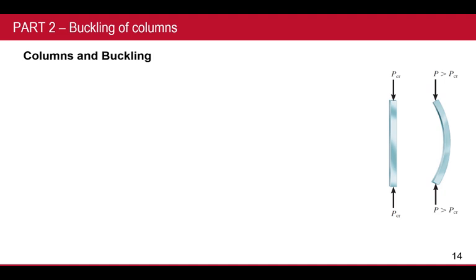However, in many cases, the yield strength is not always the only way to do it, especially in some special situations, for example, for columns. For many columns, we need to consider the safety requirement, for example, stability. So of course, strength alone is insufficient for design.